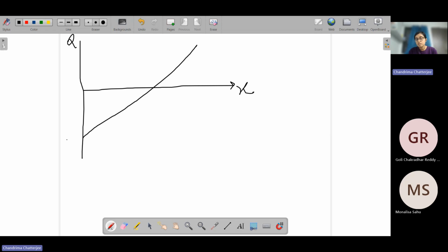This is minus Q, this is plus Q. Another thing is for symmetric line, you will see Qs is equal to minus Qr. Their magnitudes are same, just that they are 180 degree apart. There is a negative sign. Okay, for symmetric line I am talking about. And the curve comes something like this.